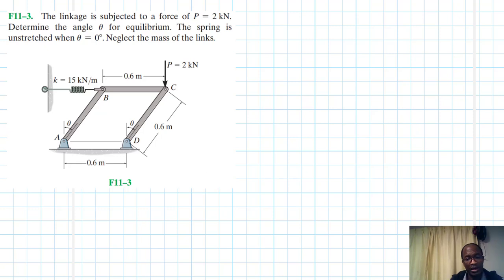So we draw the free body diagram. Here we expect a reaction force in that manner. This is a hinge, and also there, we expect a reaction force like so. And then here, let's say we cut this particular spring, so we are going to have some tension or some spring force in that direction, and there in that direction like so.